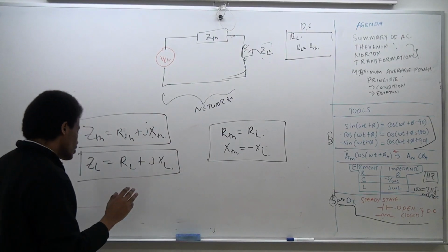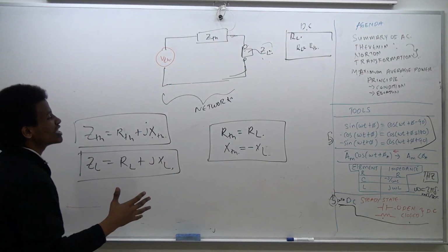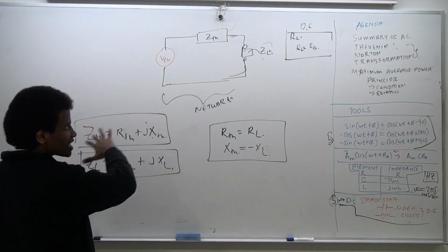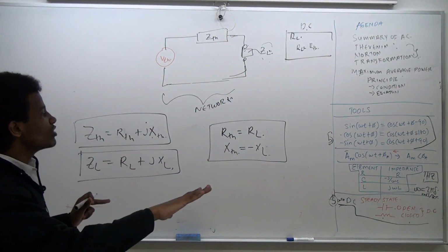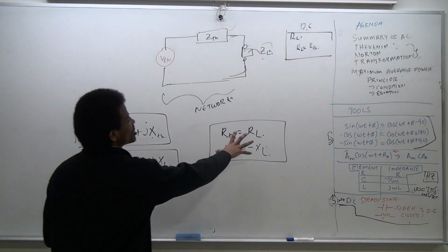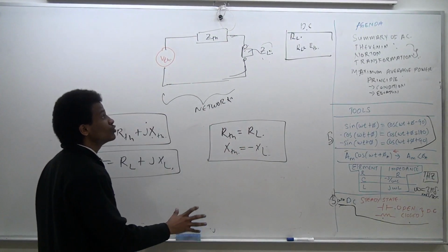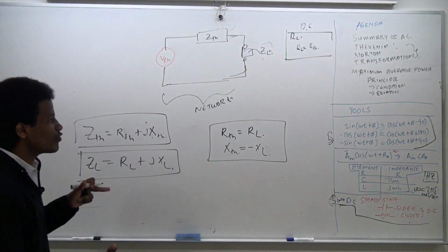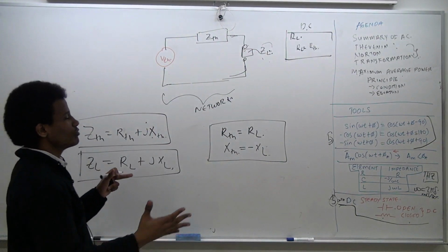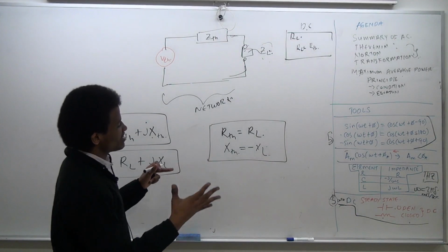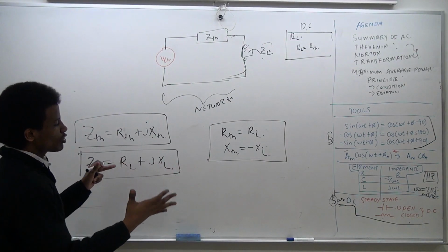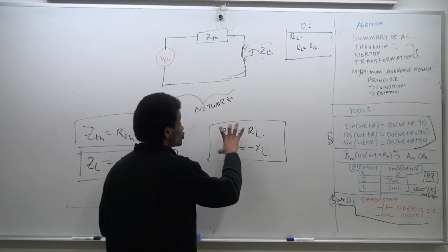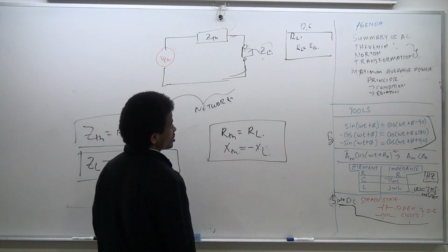What we are doing is analogous to transforming all the complex power into purely real power. That's why this condition exists. In fact, if somebody did not do the optimization problem but has a sense that power could be imaginary, could be real, and both domains exist simultaneously, and one could be exchanged for the other, you could get this answer without doing the optimization problem.